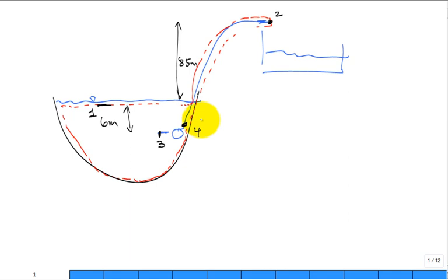Well, some of us have picked a control volume that goes like this. Just like here, it comes down, but then it cuts right there and goes up. That control volume will work. And when you draw that control volume, it's critical whether or not the pump's in it or not in it. Because if you leave the pump out, it's like a free body diagram with some forces or loads. It's not going to get the right answer, right? So that control volume will work.